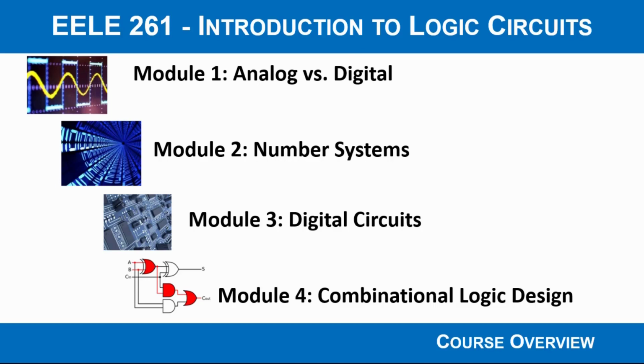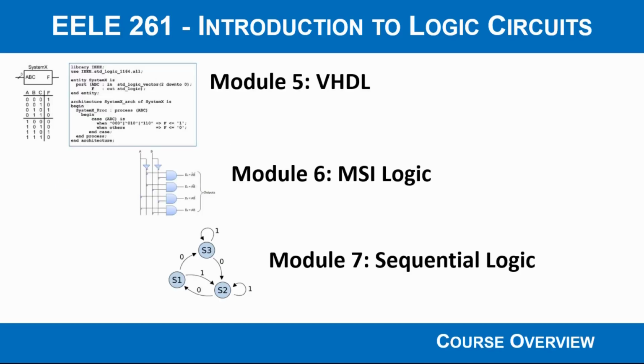Then what we do is we move into Module 5, which is where now that we know how to design a logic circuit, we kind of take a different direction and we start learning about a hardware description language. So it turns out that while we learn about how to design logic circuits on pen and paper and we actually can breadboard them and wire them, logic circuits get really big really fast. And so it becomes impractical to be able to model a modern digital system on paper using schematics. So we have invented this thing called a hardware description language, which is a programming language that allows us to describe the functionality of a logic circuit.